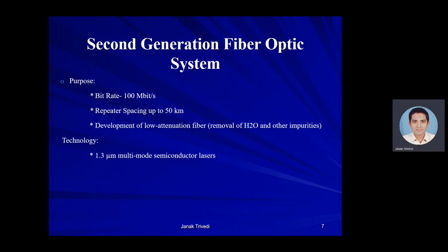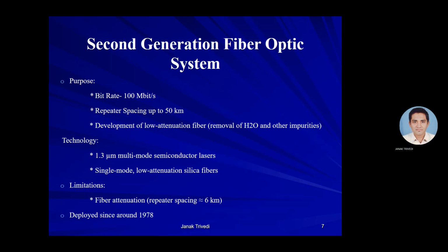It uses 1.3 micrometer multimode semiconductor lasers and single mode low attenuation silica fiber. Its limitation is fiber attenuation, which requires repeater spacing of around 6 km. This kind of system was developed around 1978.